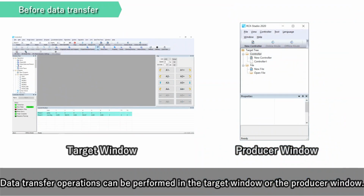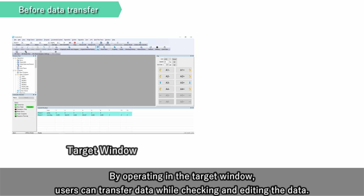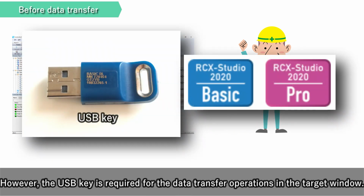Data transfer operations can be performed in the target window or the producer window. By operating in the target window, users can transfer data while checking and editing the data. For this reason, this is a recommended method for those who edit data at installation or maintenance. However, the USB key is required for the data transfer operations in the target window.